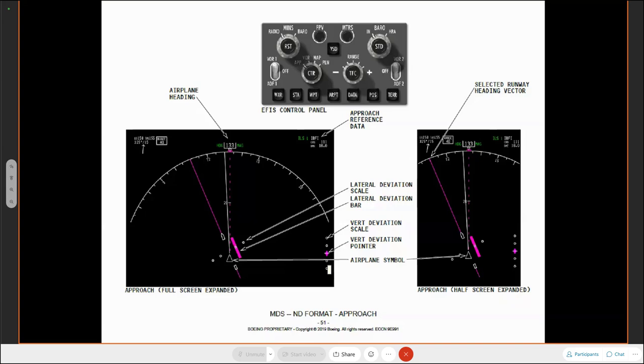And again, as you start to line up onto the runway, then this bar will start to come more centralized. This pointer here is normally selected to the course of the runway. So on your mode control panel, as part of their checklist for landing, they would have selected the actual course, the heading of the runway they're going to land on. As this starts to move in, this will also start to turn because we're making our approach. We're going to intersect the localizer, okay?